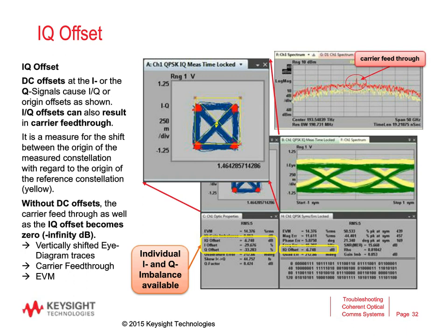Another quick check that you could do on the instrument is looking at the spectrum. So in case you have DC offset in the signal, you would see a little carrier spike here in the middle of your spectrum. The red one shows actually the carrier feed-through, and the yellow one does not do it. So in the case of the red trace, I'm looking at a distorted signal where I have some DC components running in the modulator.